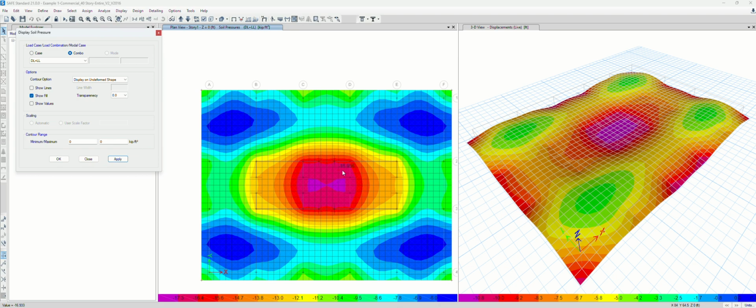Under the middle, because our concrete wall is pretty heavy, I think the wall carries a lot of gravity loads from the whole 40-story floors. So it makes sense that at the middle they're going to receive the maximum dead load, which creates the maximum soil stress here.